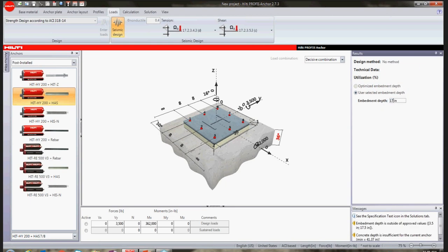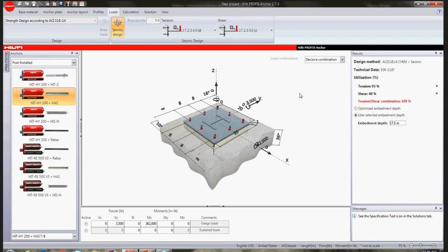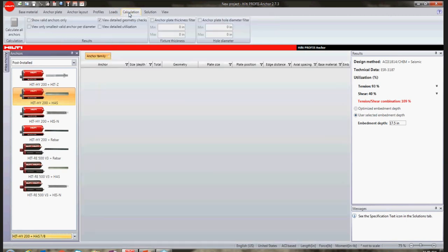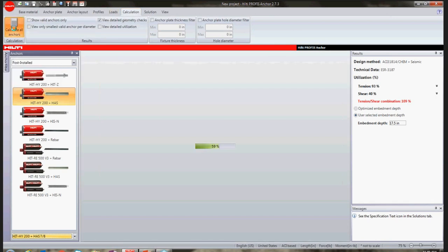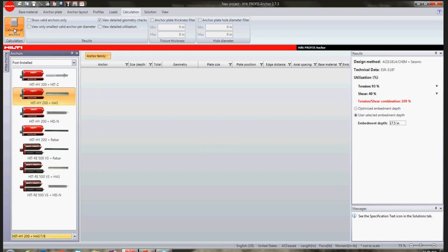Restraint. So we're not allowing for that fixture to rotate. Some of you may be going, okay, how do I calculate this? Well, this comes from the European Technical Approval Guidelines, where we're looking at flexural bending, because there is no standard in the United States to account for flexural bending on an anchor system with the standoff application.